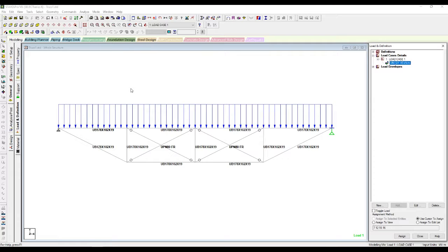First, what I'm going to do is run this case, see what loads or stresses I'm obtaining here: moments, axial forces, shear. Then I'm going to use my MATHCAD spreadsheet to tell me what the utilization ratios of those elements are.